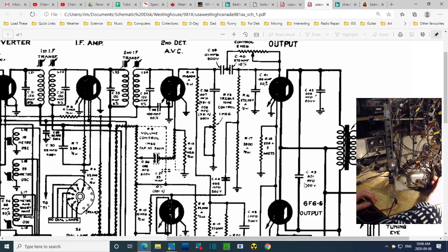Double checking again. So, whoa. Here I'm getting, I know you can't see it, but you have to trust me, this is the 175, and on this side. Now I did test these tubes and they did not match. They're not a matched set of tubes. So their mutual conductance is different. That would mean their operating condition would be different, and the quiescent current going through them would be different.